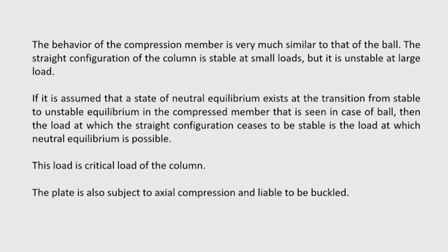After that I will show some applications, and then buckling can be considered or analyzed with the help of this equation that we will derive today just by changing the sign of the in-plane load. Taking the lateral load to be 0, because buckling is always a homogeneous boundary value problem. So, there will be no external load in case of buckling, only the axial forces are applied in the buckling analysis, and we have to find the value of this axial force as the critical value.